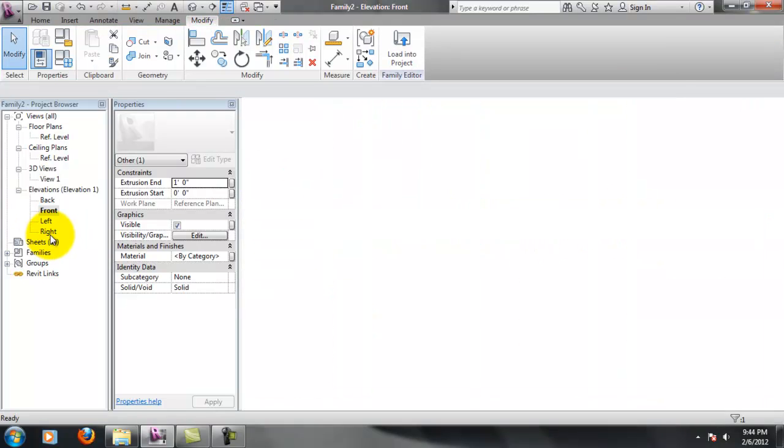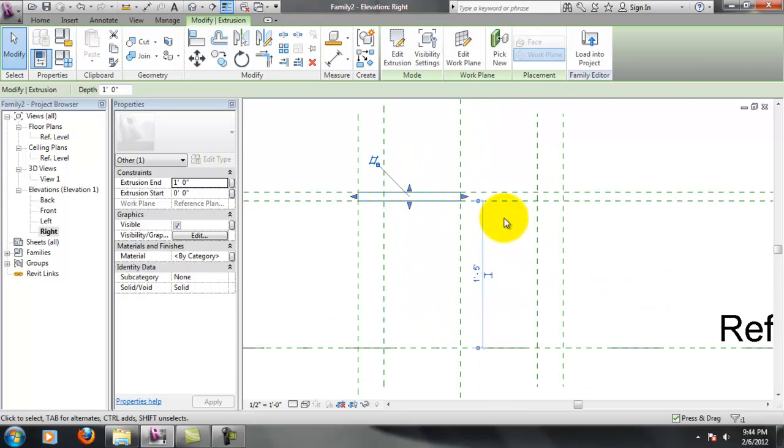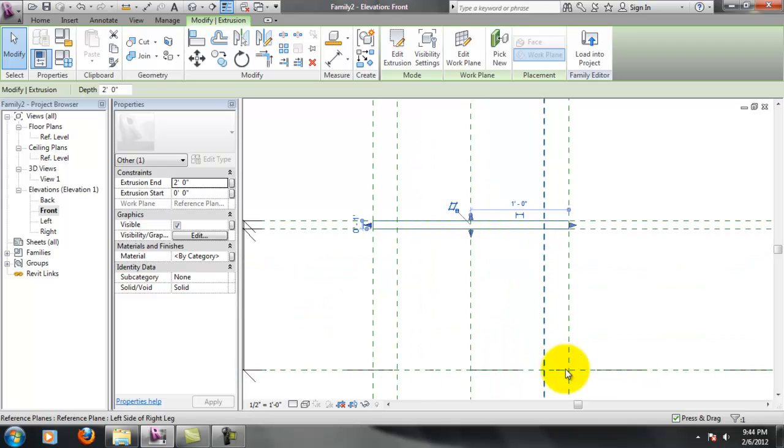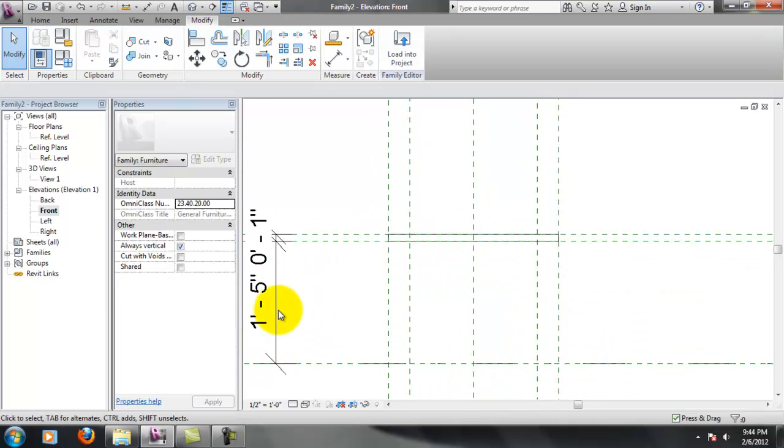And if you remember, because we created our geometry, we can jump to the right side now and just drag this arrow over to the back of it. And remember, after I do that, I'm going to lock it by selecting this lock. That locks the back of this extrusion to this grid line. These other ones are automatically locked because I locked them during sketch, so this is the only check you should have to do when altering this. Okay, so I'll jump back to the front view. I'm going to delete this guy, I'm not sure why it was there.